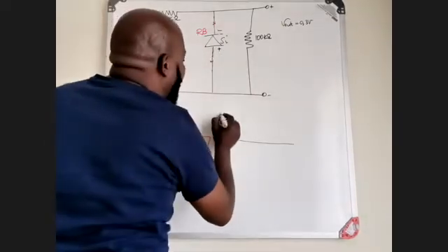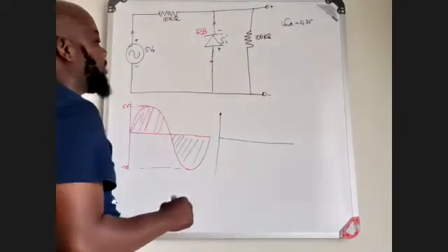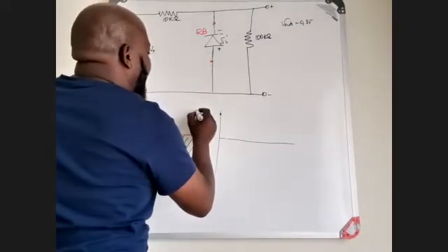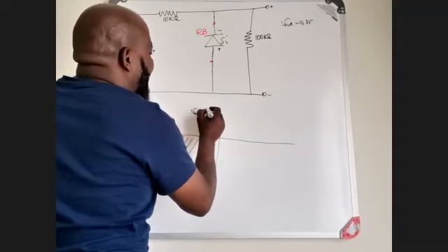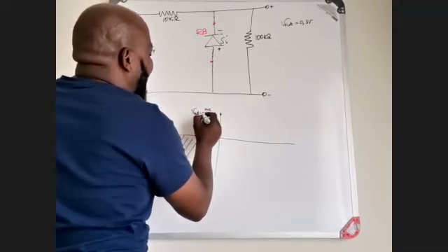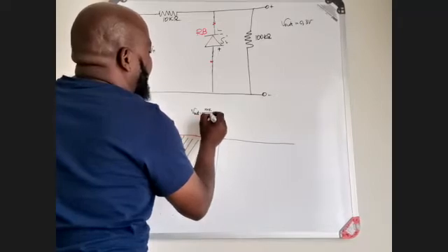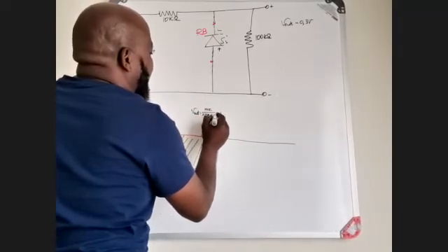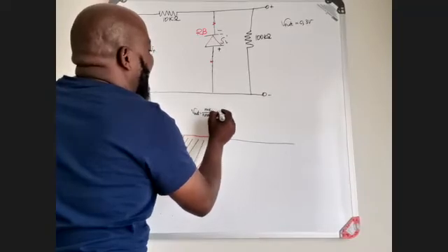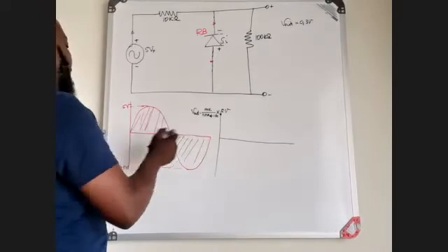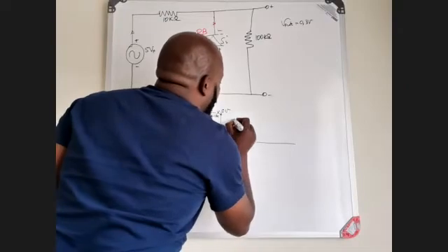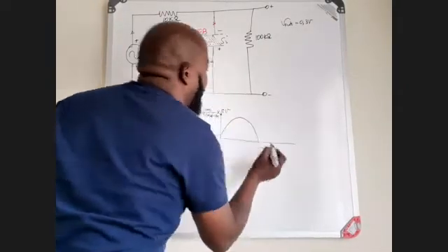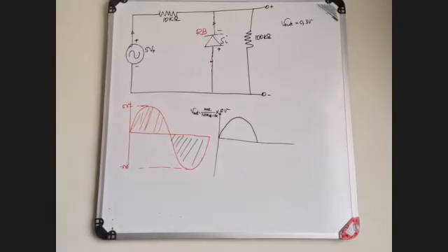When I look at this, V out will be given by your 100K divided by 100K plus 10K, multiplied by 5 volts, which is your positive 5 volts. Which means this input positively is going to be allowed to go through.